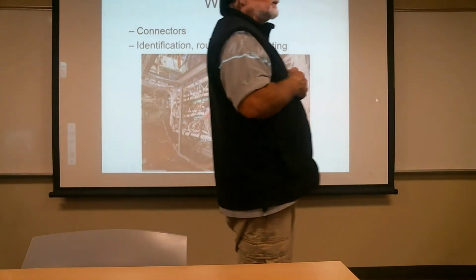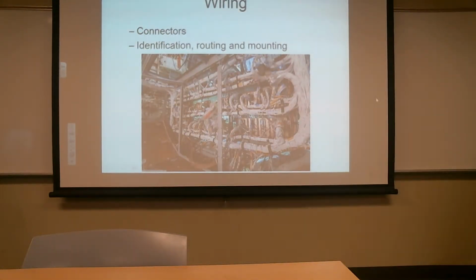Okay? Now, the preponderance of electrical problems are at or very near the connector. So that's one reason they're our friend. But the other reason they're our friend is they provide us locations to do relatively easy testing from. So I can just connect a connector here and a connector there and a connector there and start testing from each of those locations to isolate down to a much narrower part of the schematic where my problem might be. Again, with the understanding that there's only 3 possible problems that can occur. Short, open, failed power source. Right?